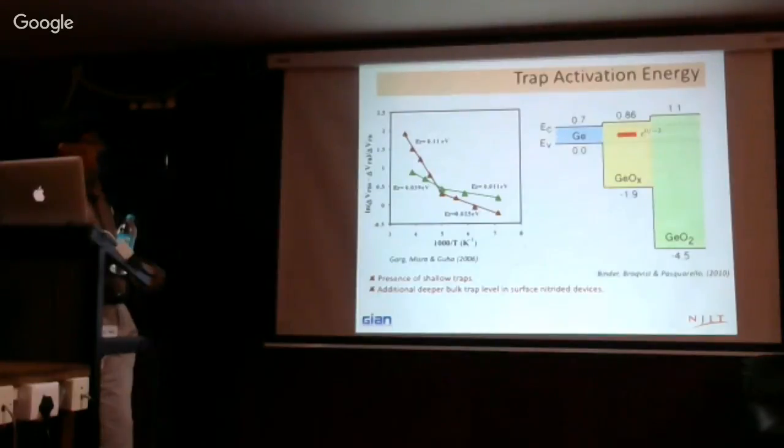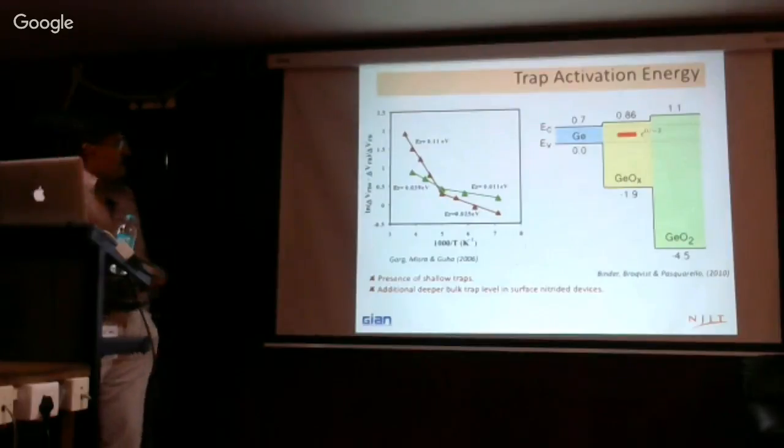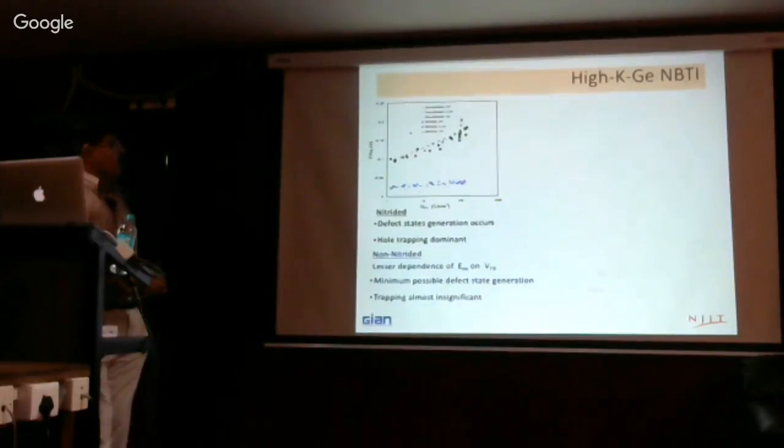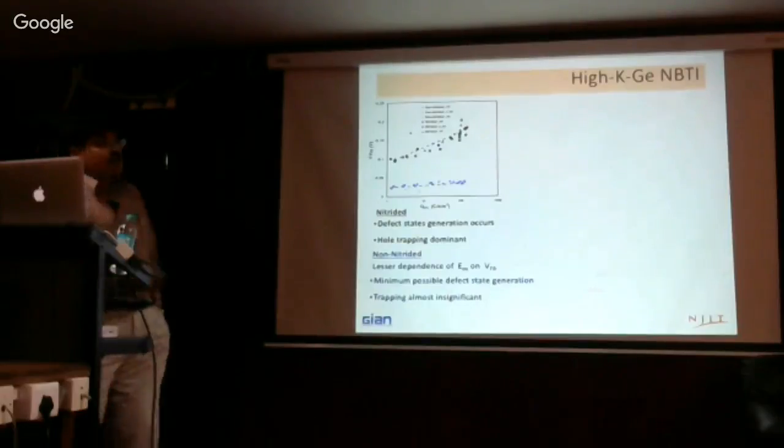And then if you look at GeOx formation, in the beginning at the interface with the germanium, and you have GeO2 formation if you want to do it that way, then you also have a lot of defects coming in the GeOx. It's not a perfect dielectric. And then again you stress these things.